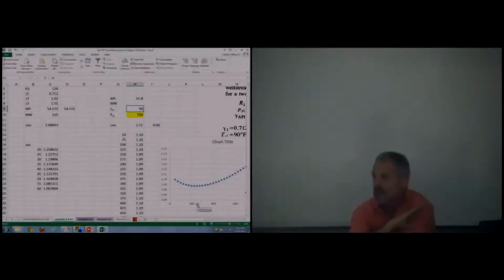So the way I would really write this question is I'd give you that data there in the second example, and I say, what is the optimum separator pressure for maximizing revenue? That's only because we were able to notice we had a local min over the operating pressures that I can probably operate this separator.